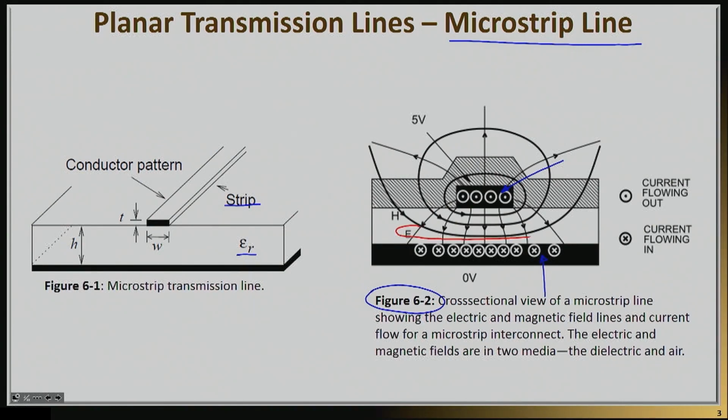So here you can see the electric field lines. And as we discussed before, some of those field lines are inside the dielectric, and some of them are outside. In this particular example, we actually have a passivation layer, which is relatively common in some frequencies, in some applications, where you're trying to protect the transmission line from any other external effects, perhaps, for example, humidity or exposure to dust.